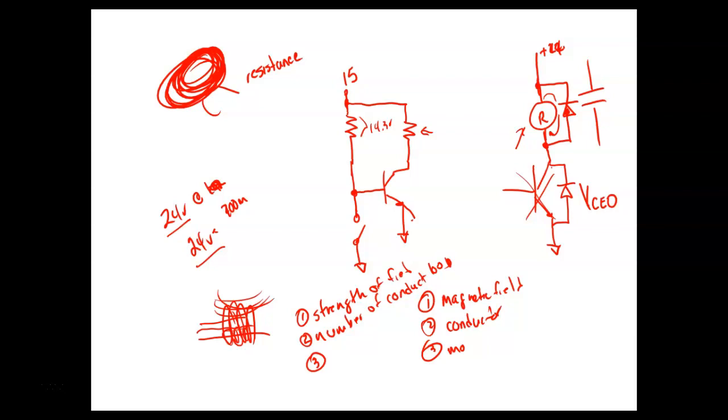So resistive loads, we have no problem. These relays have what we call inductive loads. If you take AC, you'll find out that you can charge these things called inductors. But when we turn it off, and all that magnetic field comes collapsing back into those coils of wire, it generates an EMF that would wipe out your transistor. You'll see that all the time, guys, even on PLCs. When y'all come on campus, I'll show y'all some of the relays over there on our manufacturing line, and I'll show y'all these diodes.